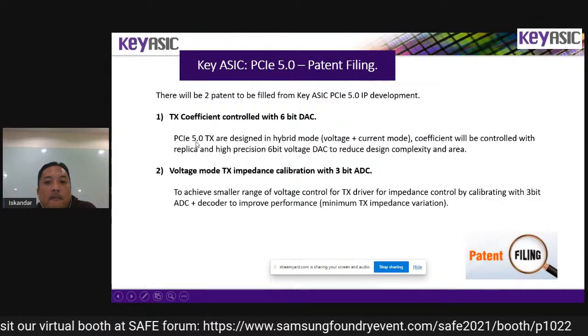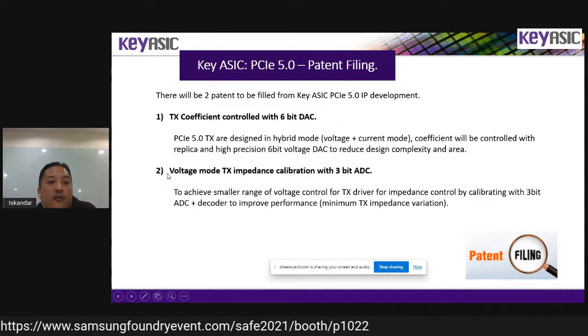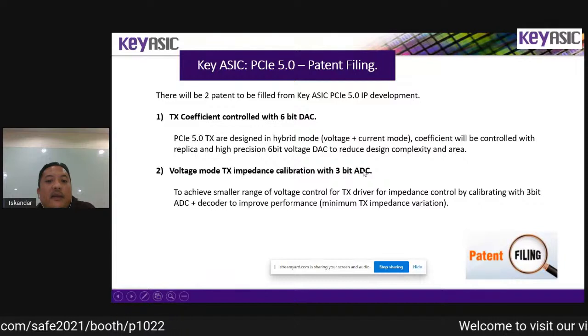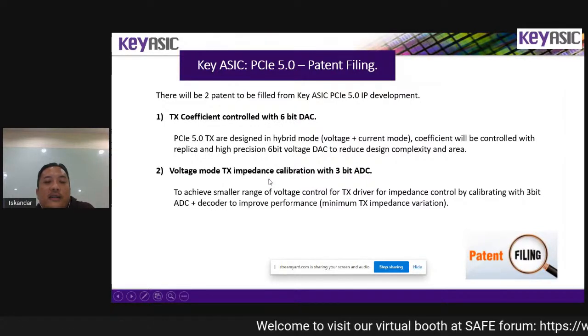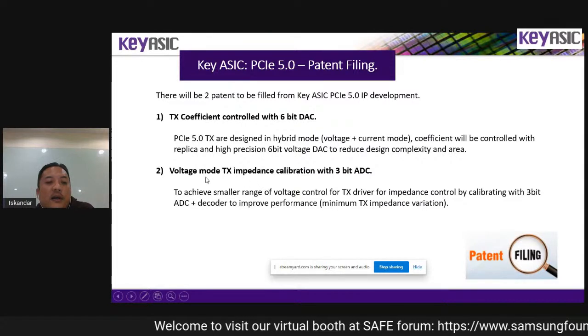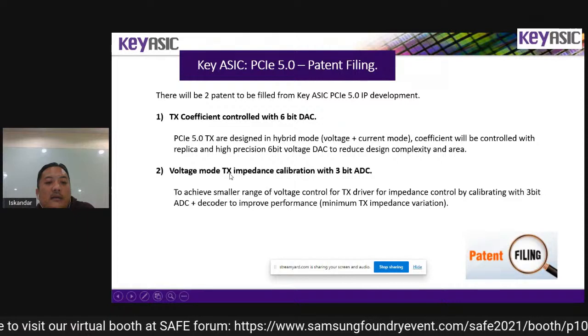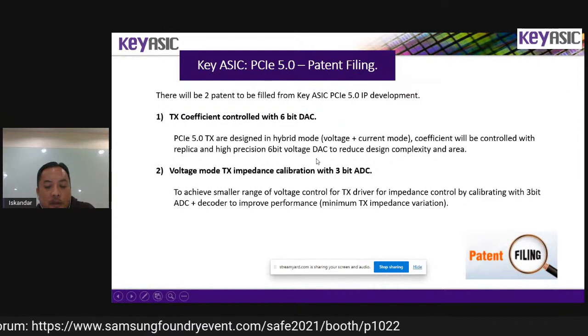So the second patent is a voltage mode TX impedance calibration with 3-bit ADC. So instead of using a few legs of digital driver to control the TX impedance, we use some kind of analog method to control the driver impedance.